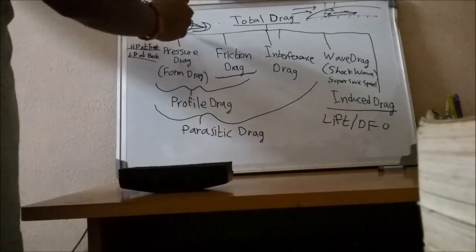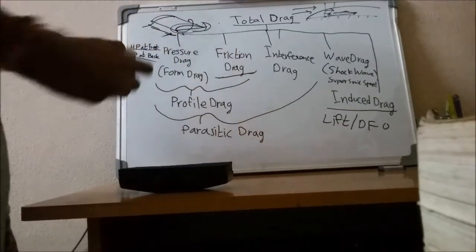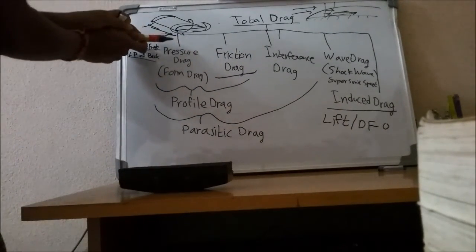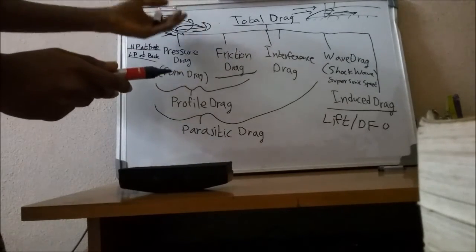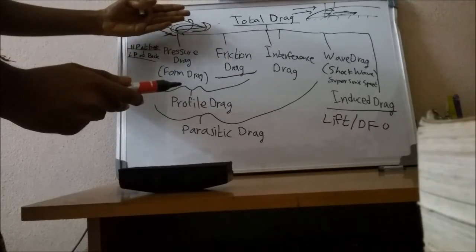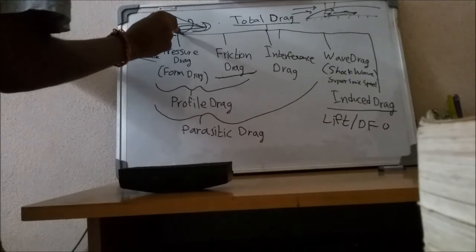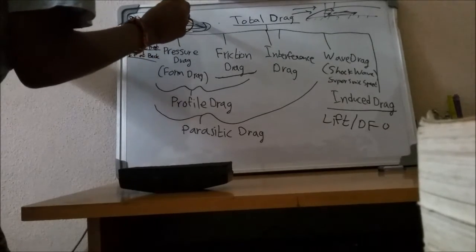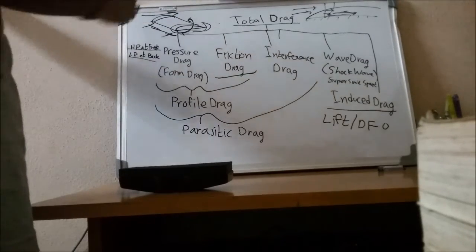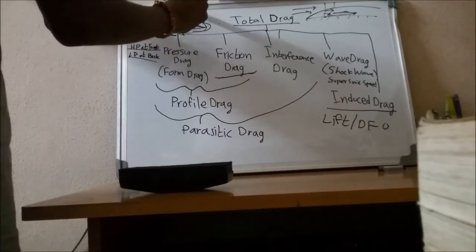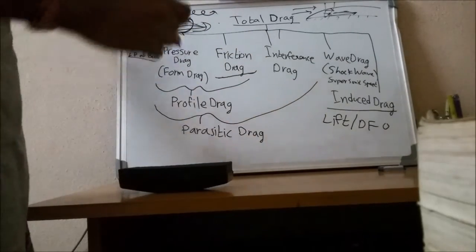Basically, say you have a low pressure area at the top of the wing and a high pressure area at the bottom of the wing, and when it comes to the edge, there is no defined boundary to separate the high pressure region and low pressure region, and the fluid tries to enter from the high pressure region to the low pressure region, and there is also a straight moving component. So it will develop a helix kind of flow, known as tip vortices.